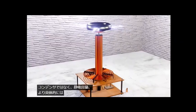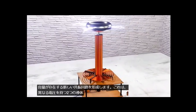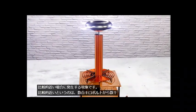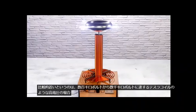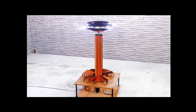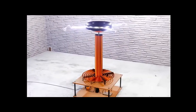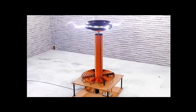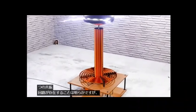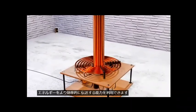More specifically, a parasitic capacitance, a phenomenon that occurs whenever two conductors with different voltages are relatively close. And I say relatively because when we are talking about voltages as high as a Tesla coil, which can reach several hundred or thousands of kilovolts, this phenomenon may be noticeable among conductors who may be several centimeters away or even meters away. Now that we are clear that two resonant circuits exist, in theory we could take advantage of its ability to transmit energy more efficiently.